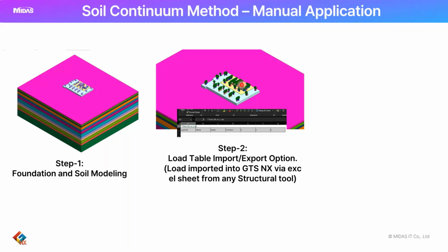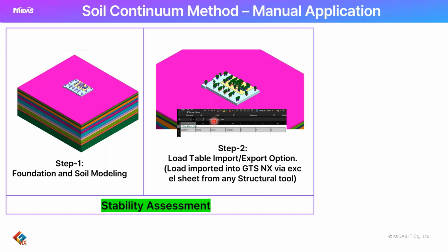So what we get out of this is we can do the stability assessment of the entire foundation. We can get the displacement, we can see the soil bearing checks, and we can see the lateral deformations and so on. So based on this study, we can get the stability assessment of your substructure. But let's say that as a geotech engineer, from this study we want to provide some soil spring stiffness to the superstructure team.